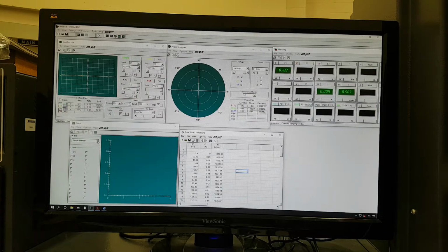On the x-axis, I3 is the field current, and this is just like an open circuit test, just like you did the open circuit test in a transformer. This is the open circuit. This is like a magnetization characteristic also we can call. So it's like I think saturation test results. So linearly it will change here, and after some time it's bending.